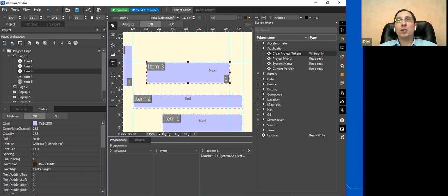On the wiki page for BACnet, you say that you need a BACnet controller. Can you tell which one, brand, model? Any BACnet-supported controller, because we have a universal BACnet driver. And of course, we work with some controller, because we are not a controller. We are not a master. We just ask a controller about what is stored in this controller with a variable.